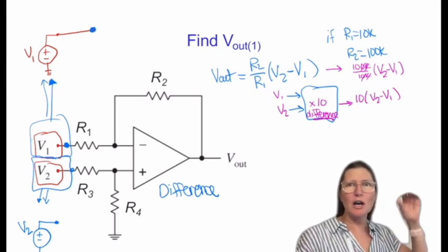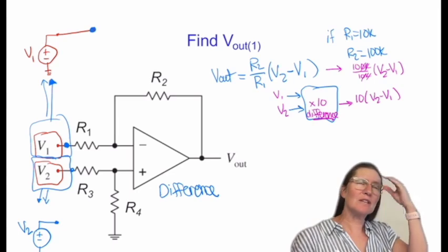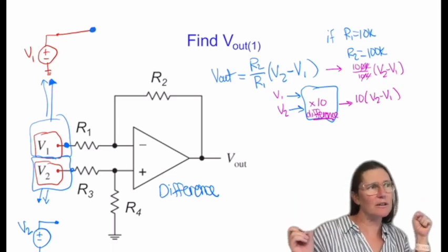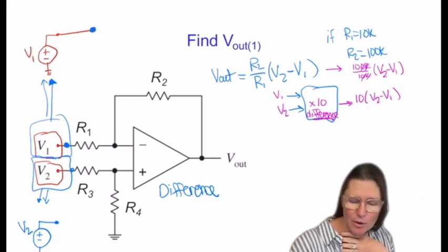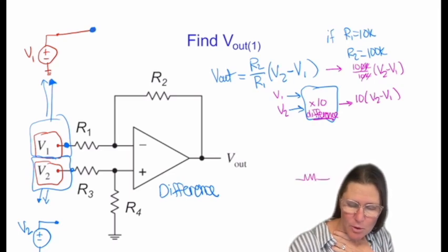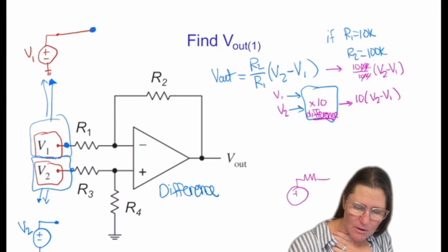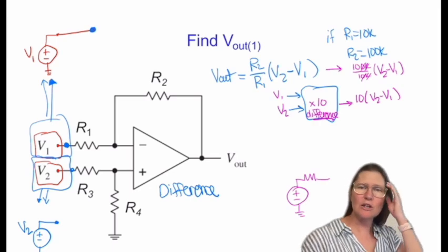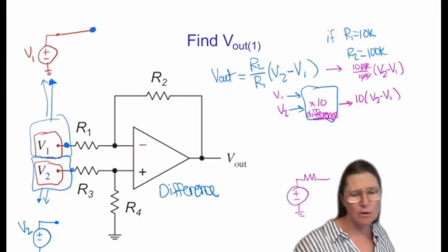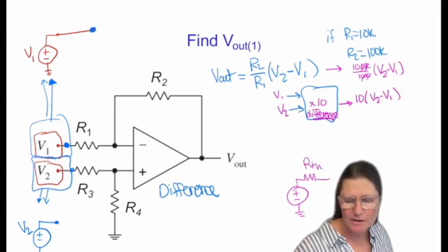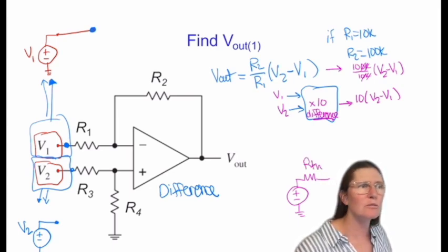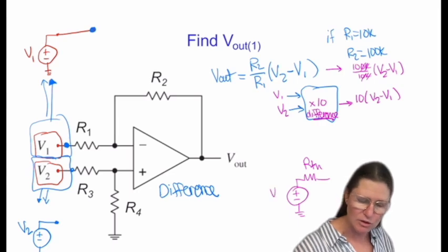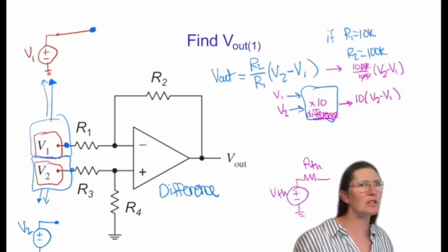Unfortunately, when you hook up any type of sensor, you get something called a loading effect. Most sensors internally can be modeled with that Thevenin equivalence. They have some type of internal resistance, and then they produce usually some type of voltage, so we call that output voltage from the sensor VTH.